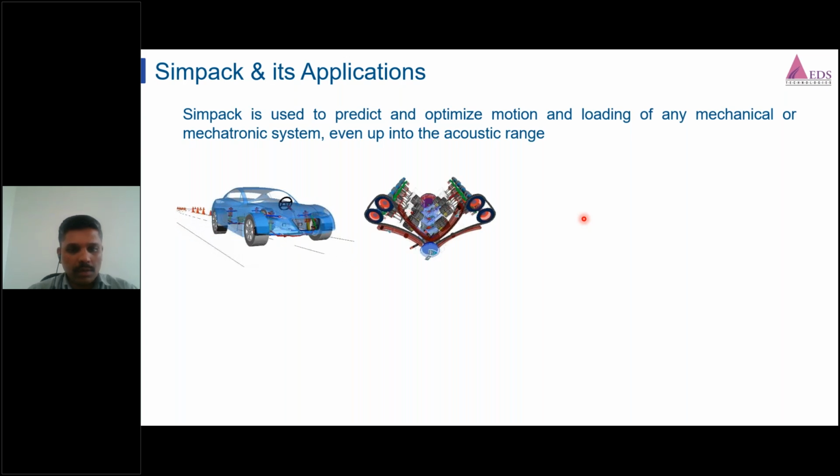Next is a complete combustion engine. It is a complex system and it has almost 100 moving parts, including flexible chain guides, flexible crankshaft, flexible valve spring, flexible camshaft, etc. So there are a lot of details. Also hydraulics for the hydraulic lash adjuster to keep the contact between the camshaft and valve springs.